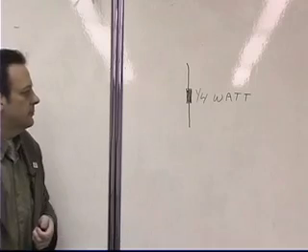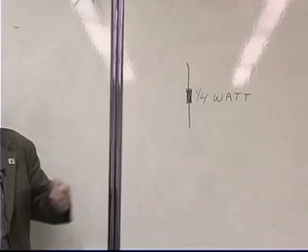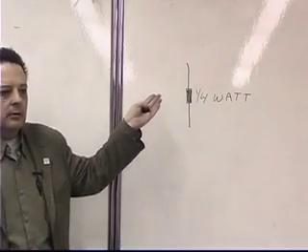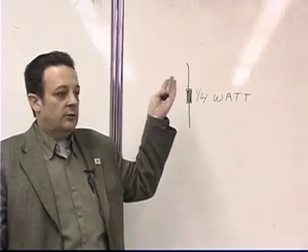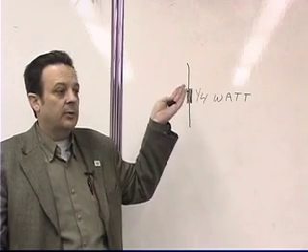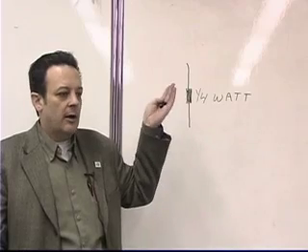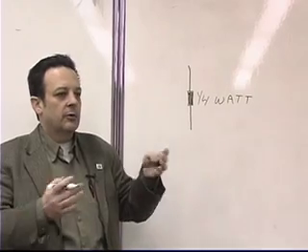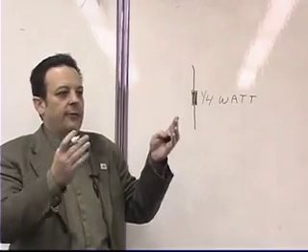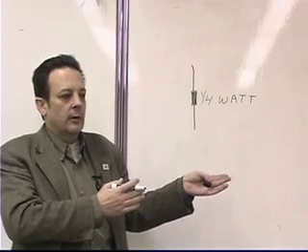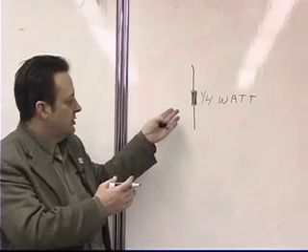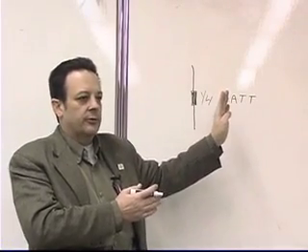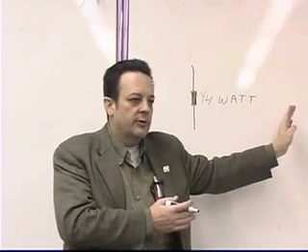resistor, then what that would mean is that that resistor is designed to operate at 0.25 watts of power dissipation without overheating, without catching on fire, without fusing and burning up. In other words, it's designed to operate at that particular power level. Okay? There are resistors that are made that are 1/2 watt resistors. There are resistors that are made that are 1 watt resistors.